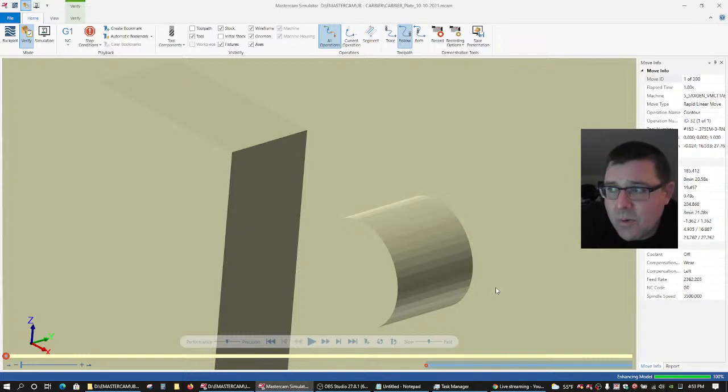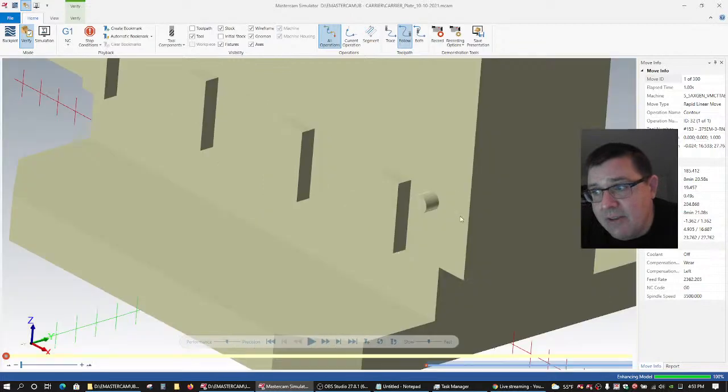But also, a lot of times we use tolerance values that are restricting our performance. So for a stock tolerance for something like a roughing operation, I'd use 4 thou, 10 thou, 12 thou, something a little larger than just 1,000th if it's just a rough initial piece of stock. Use tolerance to your advantage.